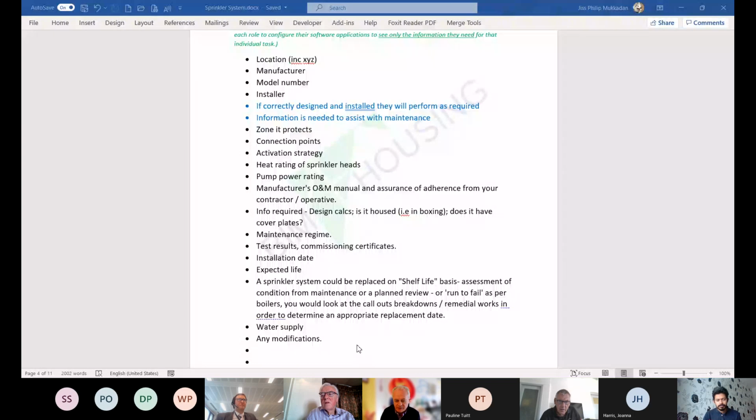You've got this awful environment. You've got moisture in there, because the way you test these things, you fill them up with water, pressurize them to check they don't leak, and then you try and drain it all out. Of course, you never quite do. And then you fill it up with compressed air. So you've got moisture, compressed air, so you've got 3 times the usual oxygen concentration. So guess what? Any risk of corrosion, off it goes.